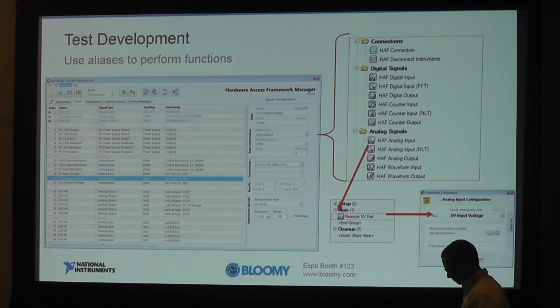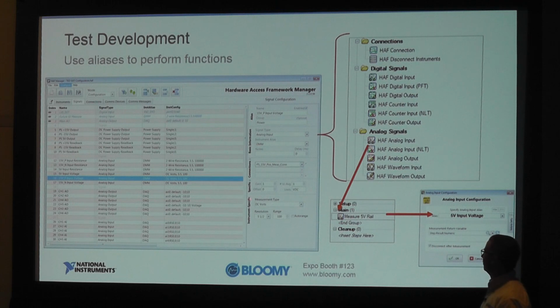And actually, I'm not showing it here, but in the measurement type here, we have thermocouple as well. And as soon as you choose thermocouple, it gives you possibilities for what type of thermocouple and a few other options. Or I said it gets temperature, and then when you choose temperature, it says thermocouple or RTD. And when you choose thermocouple or RTD, it gives you more options. That's all just coded into event structures. It's all hard-coded as part of that driver interface. So that's why it's so time-consuming.